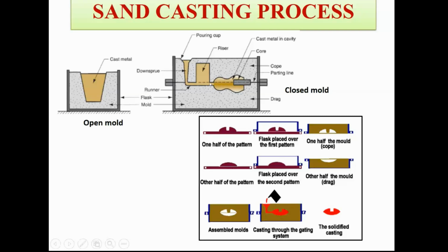To overcome this solidification shrinkage, the material filled inside the riser comes out and fills the space created at the surface of your casting, and then your casting will be of the required size as you have calculated in the design phase. So you can see that during the solidification process, the riser should be the last portion to solidify. It should not solidify first.